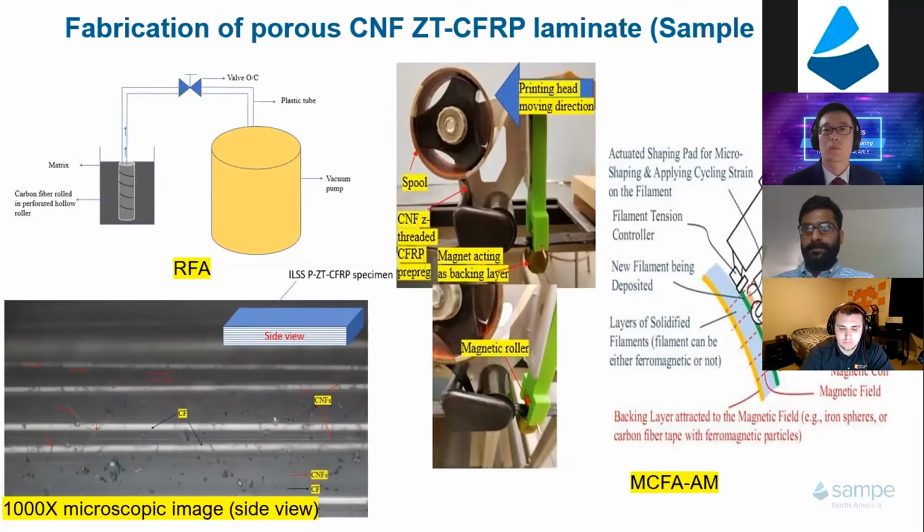Okay. Sounds great, but then you try to mix the nanoparticles, align them, and disperse them by sonication in this high curing rate resin. It's almost like you put an ultrasound probe on and it's cured right away. So it causes a lot of trouble to handle this fast curing material. A low curing speed for OABBO is fine, but when you move to a high curing speed resin for additive manufacturing, it's a totally different story handling the nanoparticles.